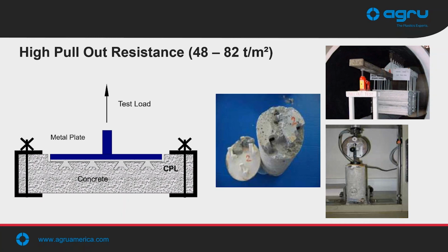But this is a back pressure test on how we would measure the strength of the liner, or the ability of the liner to stay cast into the concrete. Before we talk about either this test or the back pressure test, we need to qualify that all tests are not created equal. There are a number of factors that can affect this test, and can affect it in some fairly drastic ways. One of those, which is certainly very important, is the strength of the concrete that is used.